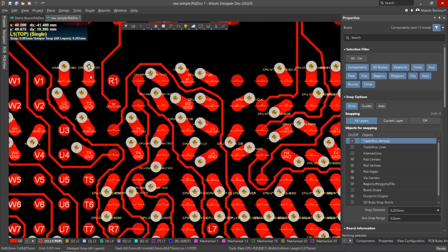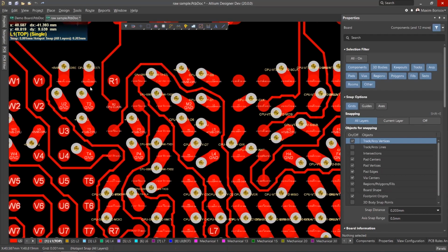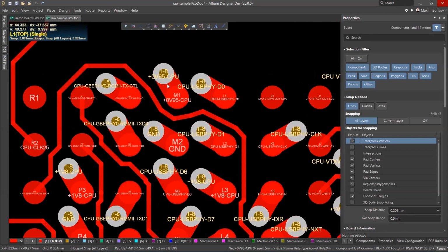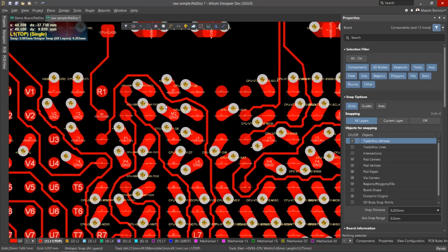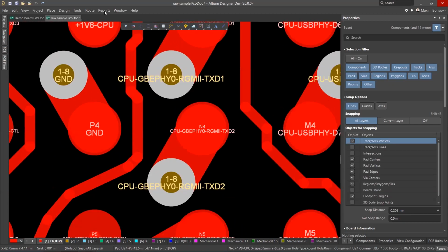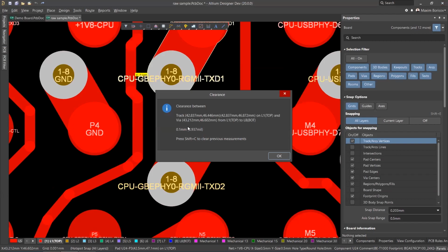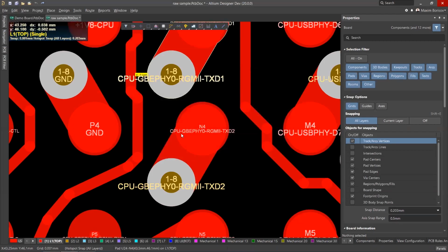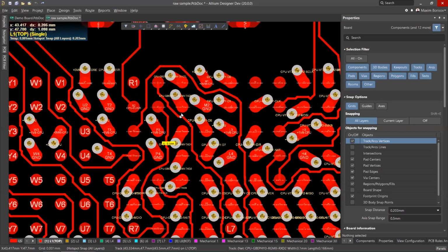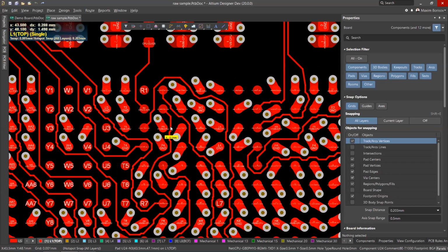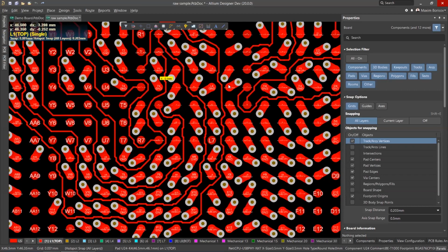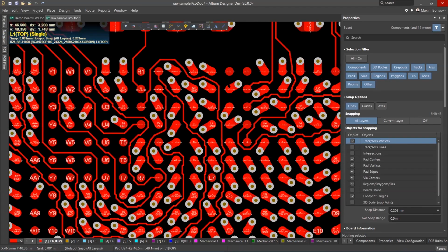Instead of 45 degrees orientation, I have 30, and reduced the distance between via and pad itself. Still, I retain reasonable clearances between objects. The minimum is 0.1, so there is no advanced technology behind that. It's just an ordinary example.